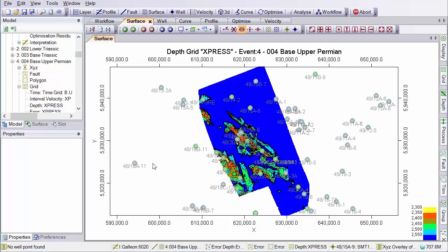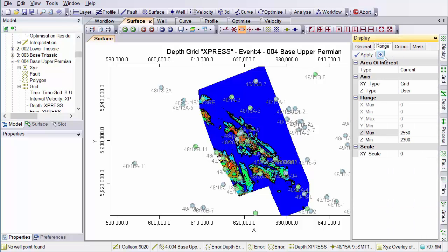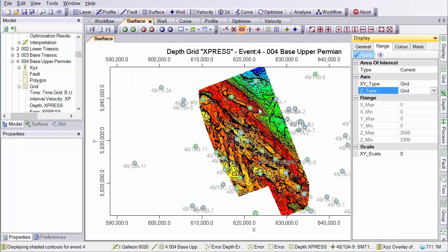We can see the structure above the contact, and this gives us a series of isolated bodies. And we can see that they're going to be approximately 250-300 meters in thickness. So when we run multiple realizations, we can actually use the filter spill routine from a seed point on the structure, which is typically a well location, to isolate connected geobodies for more accurate and useful volumetrics. So all we need to do now is adapt our workflow to run multiple times. Before I do this, I'll just set the display parameters back to automatic.